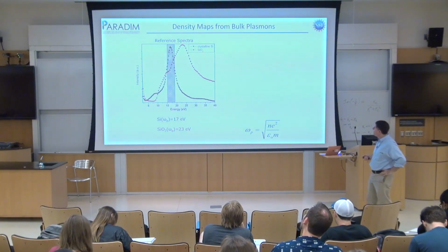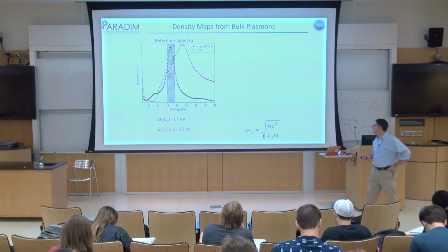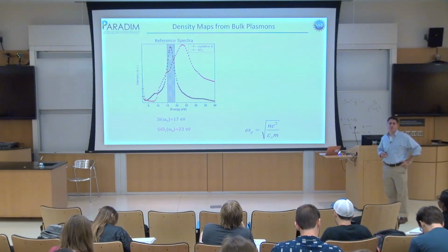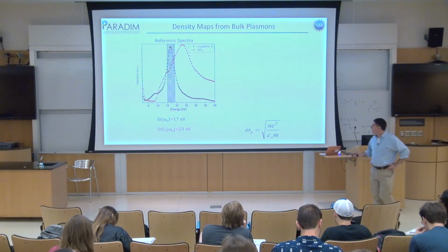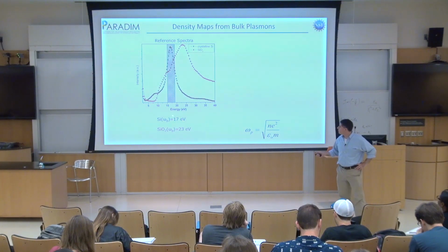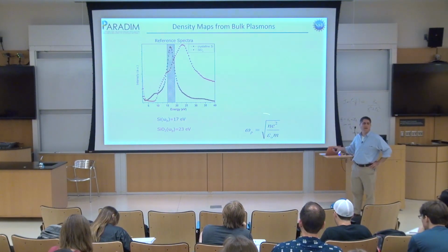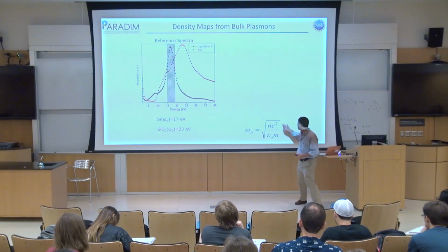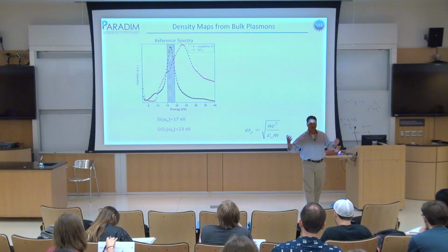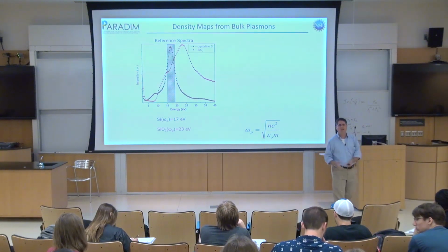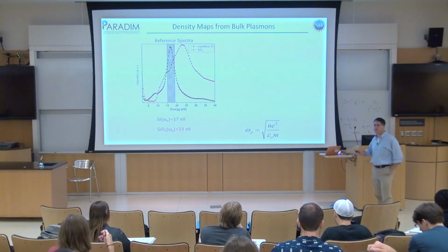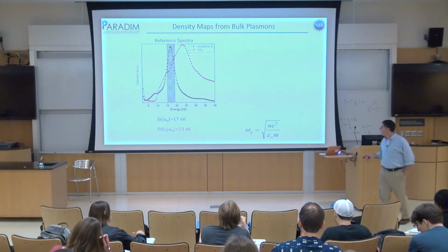Here is where in the semiconductor industry we found plasmon spectroscopy really useful. So silicon has a plasma frequency of 17 electron volts. And you'd get that just by this formula, and you can plug in those numbers very easily. Silicon has 4 valence electrons. You know how many atoms there are per unit volume. As long as you don't get the units wrong, this is easy to do.